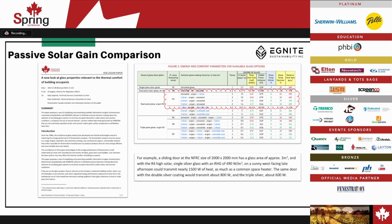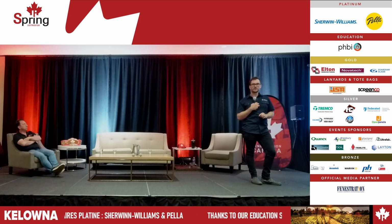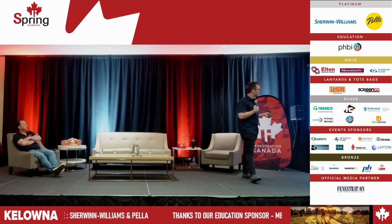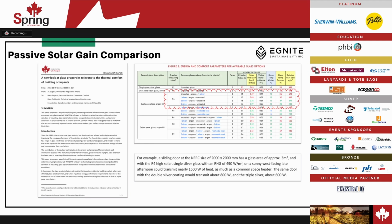That's one patio door. Can you imagine if you have a whole wall of glass facing west, how much more heat gain that's adding in? And if you compare that same door with a double silver coating, it's around 800 watts, and then a triple silver around 600 watts. So that's the power of the solar heat gain associated with comfort too.